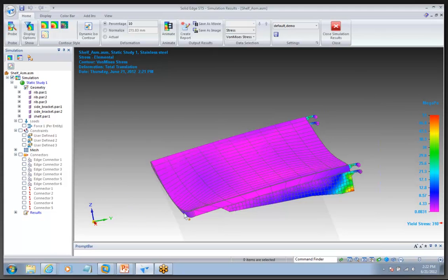The principle says that the stress and the displacement in this area will be valid, we just can't look at it in this area. I hope that makes sense. When you're thinking about what your area of concern is, you want to make sure that everything in your area of concern is included. So we're not going to say 51 is our maximum here. We're going to say the stress in this area is low enough, in the 5 to 10 range here, that it does not exceed our yield stress. And you'll see it's actually way under our yield stress.